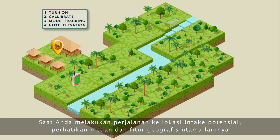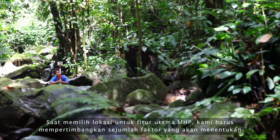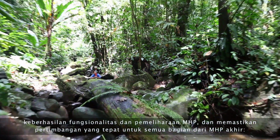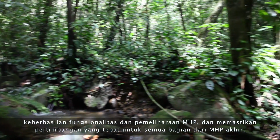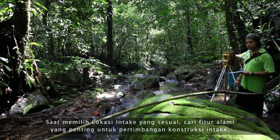As you travel to the potential intake location, take note of the terrain and other key geographical features, and potential sites and routes for the powerhouse, penstock, and forebay. When selecting sites for the key features of microhydro systems, we must be sure to consider a number of factors that will determine the successful functionality and maintenance of the microhydro system, and ensure proper consideration of all parts of the final microhydro system. When selecting an appropriate intake site, look for important natural features for consideration of intake construction.